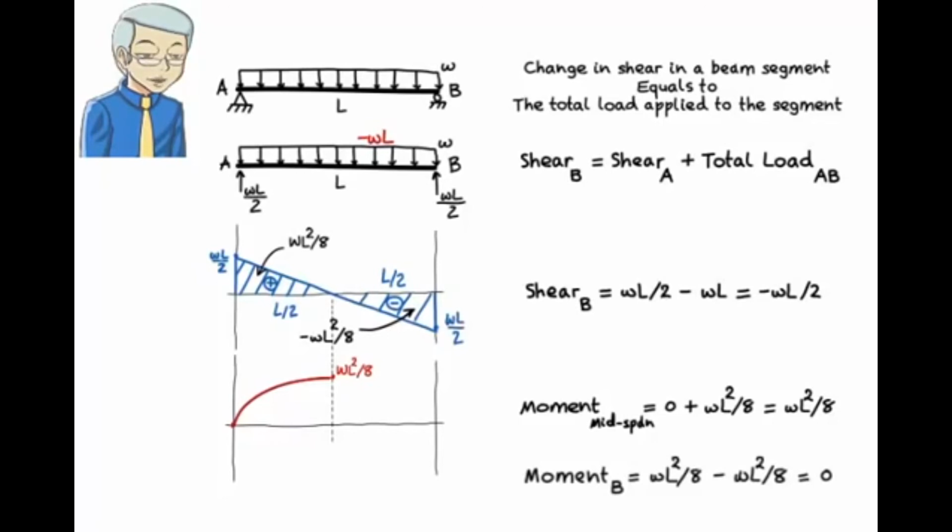Just like before, there are two options for connecting the two points: a curve with a decreasing slope or one with an increasing slope. To decide the correct shape for the diagram, examine the shear diagram in the segment. Does shear have an increasing value or a decreasing value?